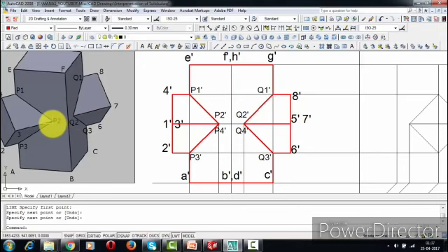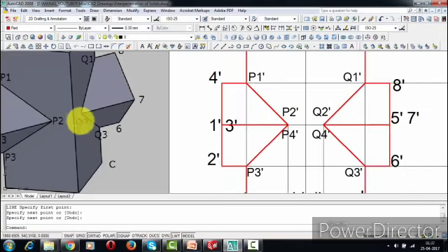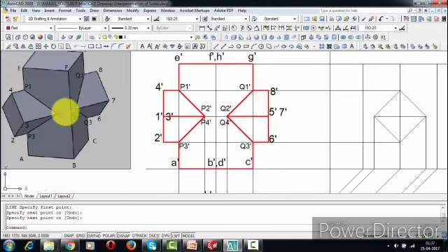Remaining portion, now the edge here, some portion of this edge is falling exactly behind the face of this vertical prism. Alright, and that's not going to be visible, and hence you have to make use of a hidden line for that purpose. I'm going to be doing all that stuff. Just be patient for a while. This edge is also going to be visible, so let's darken that also. Yeah, there you go.